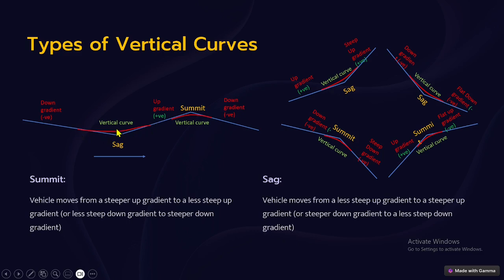If it is not properly managed, what will happen when the trains are negotiating through this connection? There will be discomfort to the passengers. At the same time, in an extreme case, it may result in some unsafe condition also. Further, the Indian Railways Permanent Way Manual prescribes in which situation the vertical curve has to be introduced, and also what minimum radius of curve you have to provide for various groups of routes. That is also available in the manual.